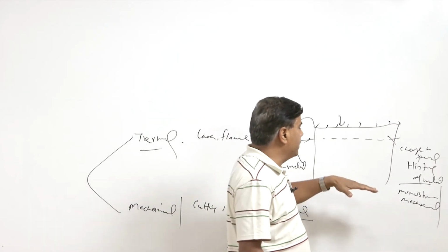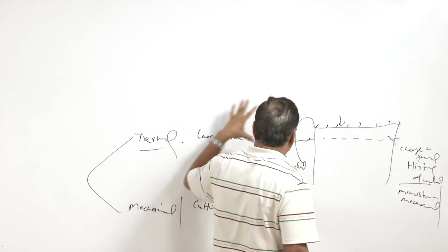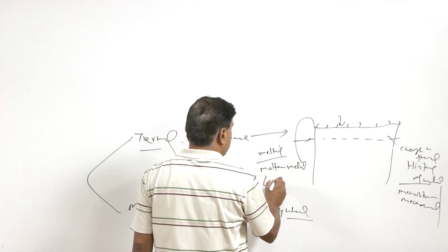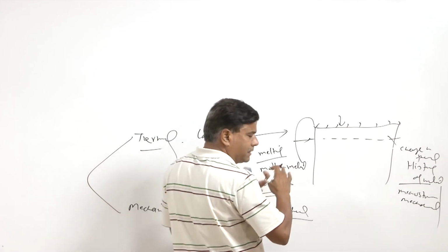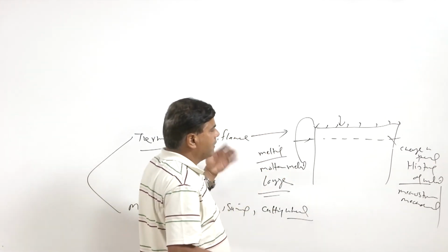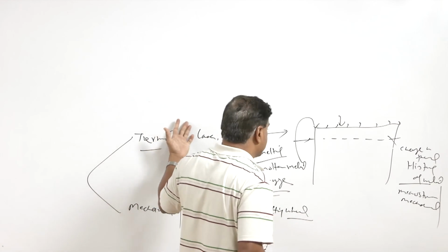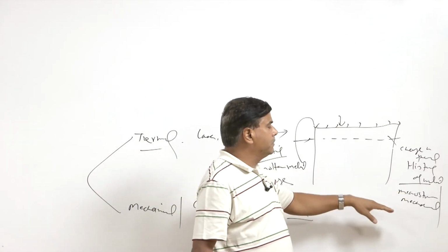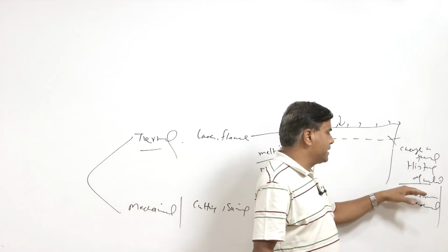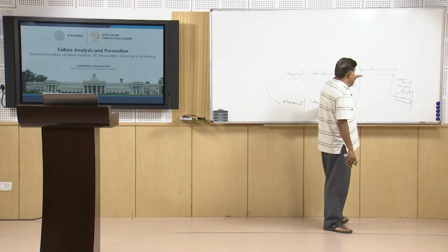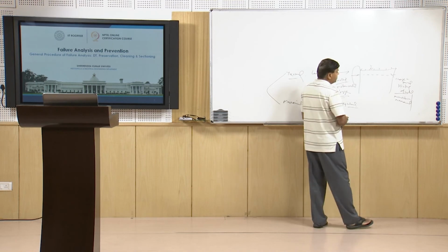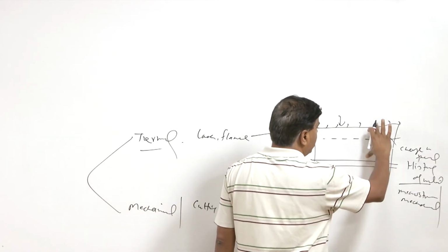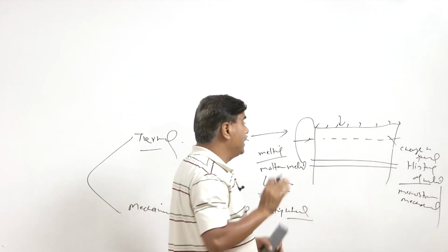So what is important is that thermal methods are used only when large size sections are to be cut, when the section size is large and samples are to be cut from it, because thermal methods are more damaging with regard to the change in mechanical properties and microstructure. If at all thermal methods are to be used, they will be applied at a much larger distance from the region of our interest.